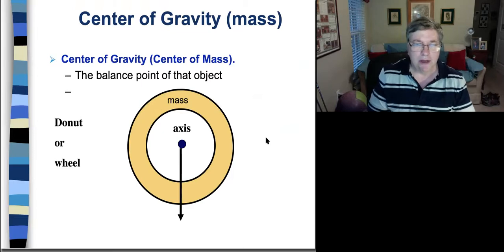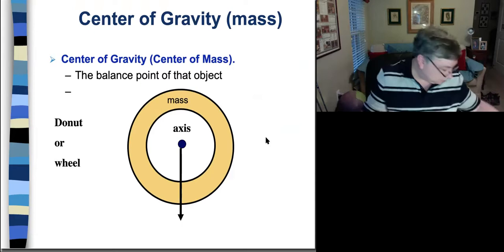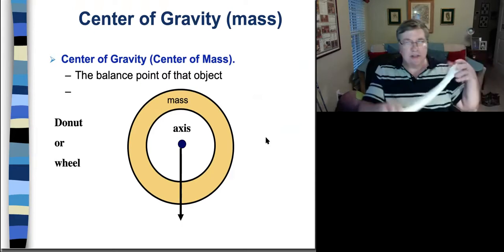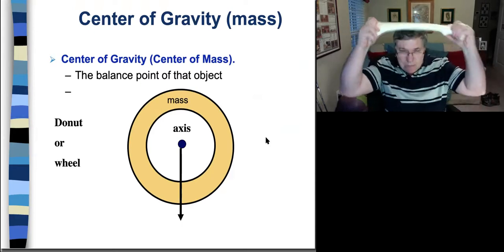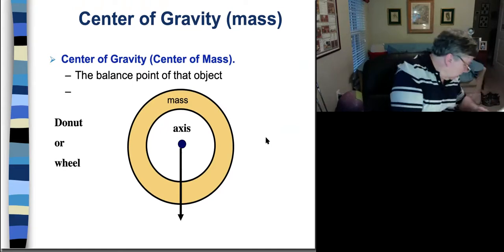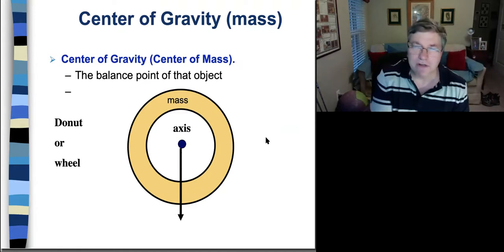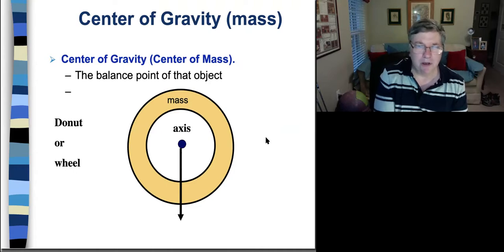So in 2 dimensions, if we can move the mass farther away from the axis of rotation, that actually increases the resistance against bending forces, torsion, as well as even shear forces, but especially bending forces. It works really, really well.